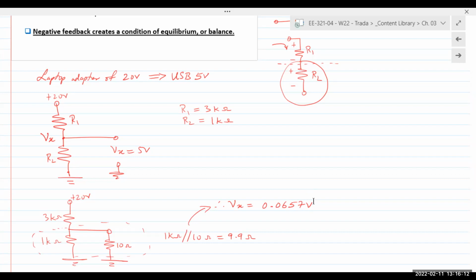So our source is basically this circuit, R1 and R2. Our load is the 10 ohm resistor. We need to isolate our source from our load. Do you all see now why I said we always want the load to have a very high input impedance or very high input resistance?